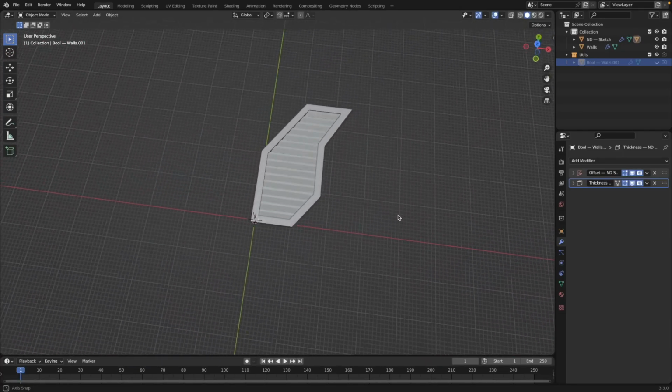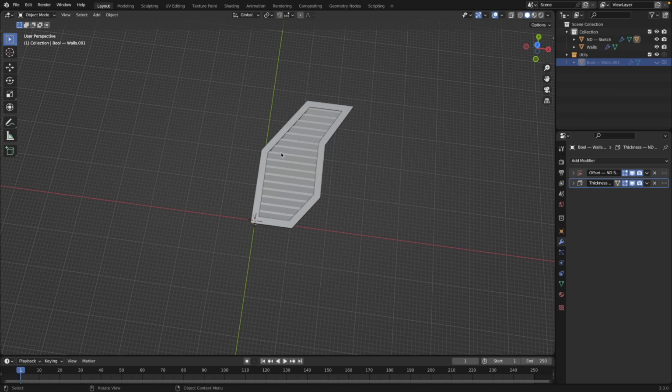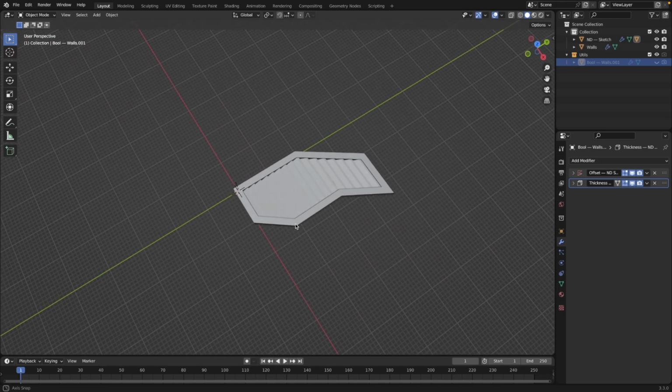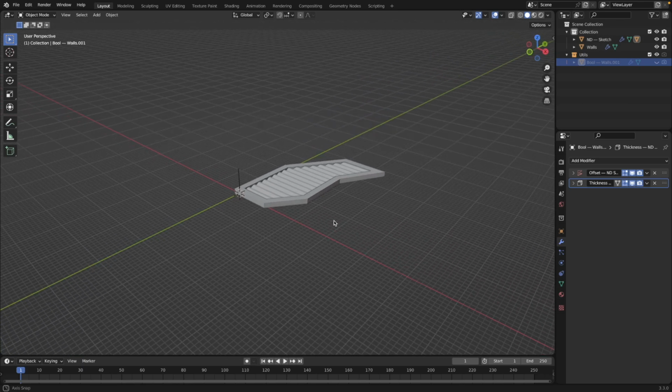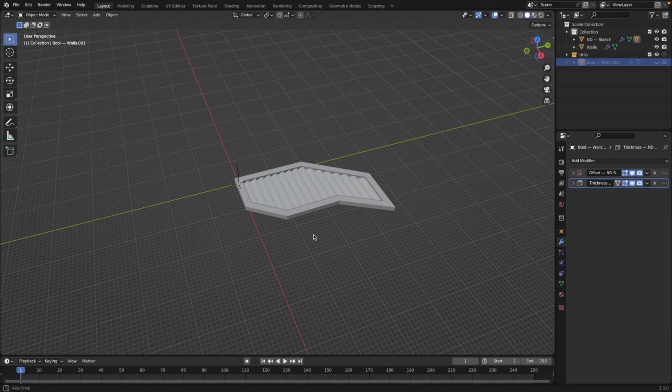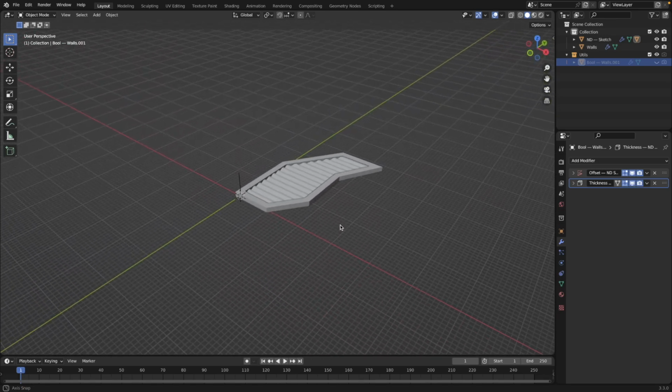So this is something you could use then to make your vent any shape you want. You could make a circle and use that to cut away. You could make this unusual shape that we just created here and use that same technique to cut away your fins so that you end up with whatever shaped vent you want. And so I think with that will end our discussion of those two questions about vents, and we will move on to the next topic.